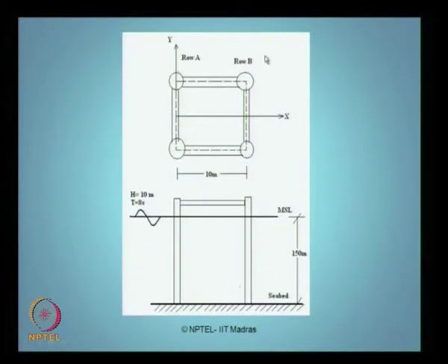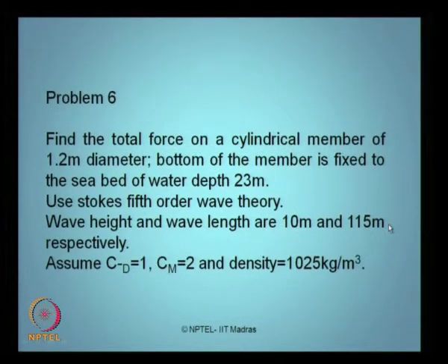So you have got 4 cylindrical members and 4 pontoon members which are spaced at 10 meter interval both along x and along y. So depth is 150 meter water depth. So I want you to compute the forces on all the members using Airy's linear wave theory.